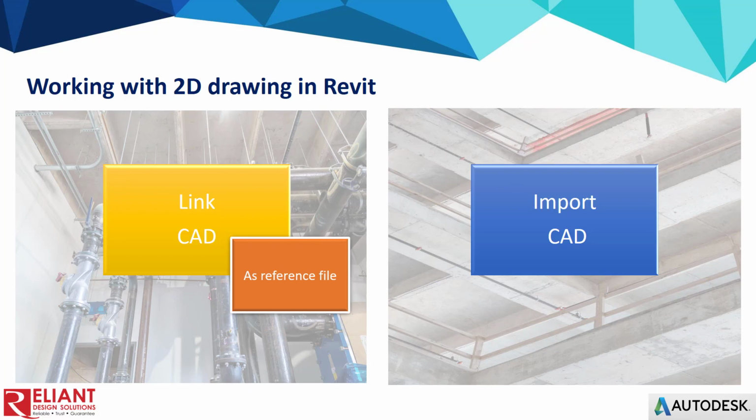You need to reload the linked file to get the new changes, while for an imported CAD file, when you import it, it stays in Revit as a part of your model. No link with the original 2D CAD drawing means it becomes a part of your project model file. So if there are any changes in your 2D or AutoCAD drawing, you need to delete the existing CAD file in Revit and import a new one back again.